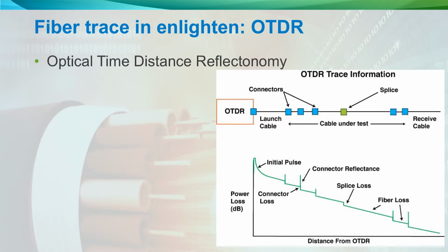Now what we're going to do is show some tracing, using the OTDR, or optical time domain reflectometer. You take a light, you shine it down a particular cable or a strand, and it will tell you where you've got splice losses and connector losses and fiber losses, and how far down this particular fiber path it works. So what's happening here is you're going through multiple different fiber cables and joints and splices and connections, and then you've got the various losses, so it will tell you you're losing signal, let's say 500 meters or 10 kilometers down this particular fiber path. When you do these connections, we automatically build those fiber paths in the background. You don't have to manually capture that. So that is the one trace.